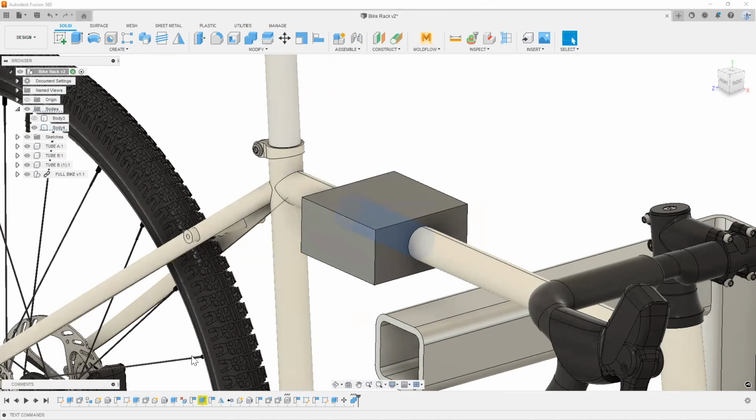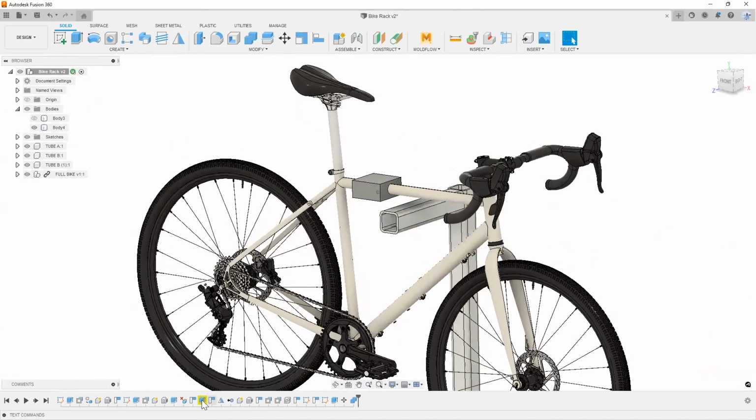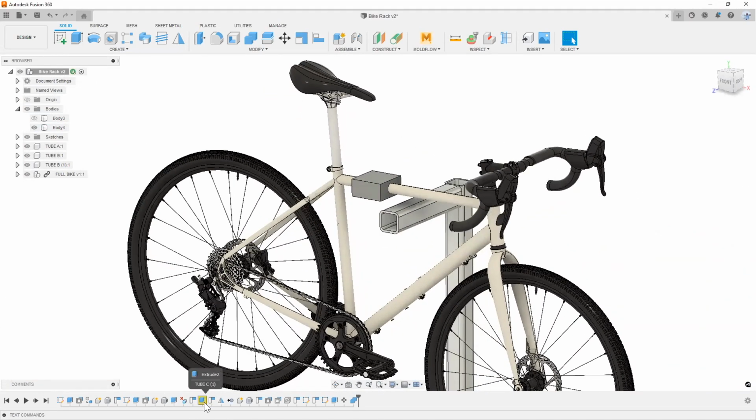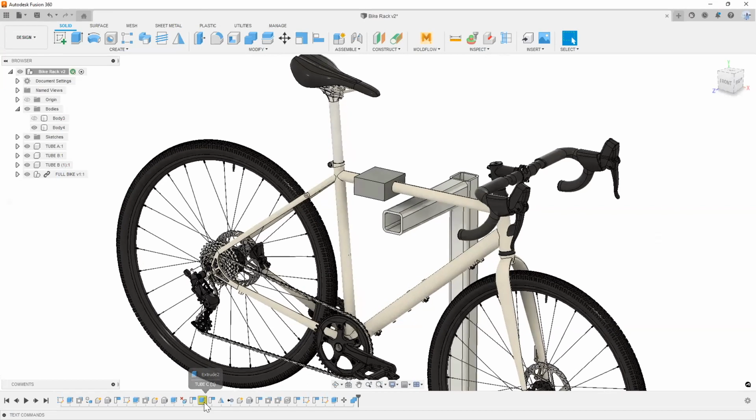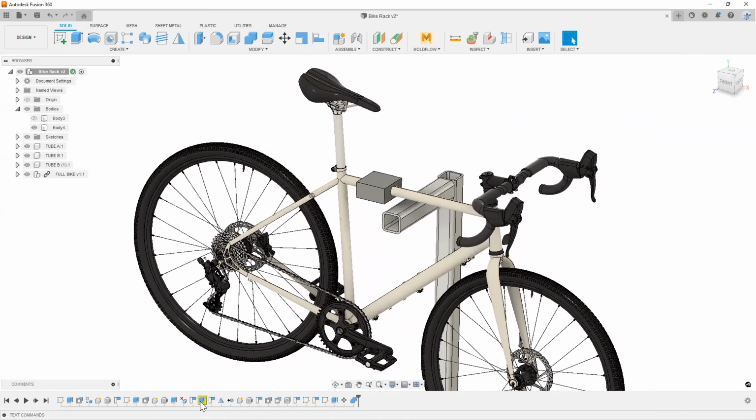Thanks for your question. Basically what happened here is I had an extrusion happen, and we can't tie this extrusion to a sketch because I may have deleted a sketch. So what you're seeing here is more of an alarm than anything. I could go ahead and either delete this feature, or the reason why it might not get deleted is because it's still tied into some sort of reference geometry that we've already drawn here. So it's pretty much just an alarm or an error that says you are missing the sketch plane for this particular extrusion. Okay, thanks for the question.